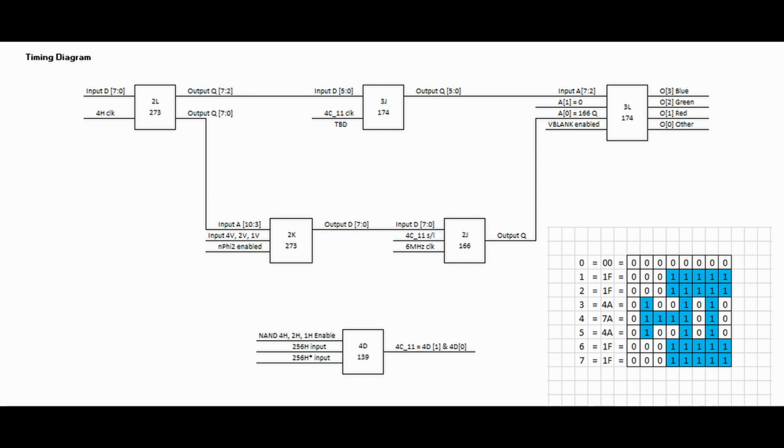The 3 vertical timer input bits make a value of 0 to 7 to add on to the reference location in the ROM. So hopefully it's now clear how the Tilemap ROM is creating the picture. It's a pretty elegant solution that only needs 1 byte to display 8x8 pixel squares on the screen.